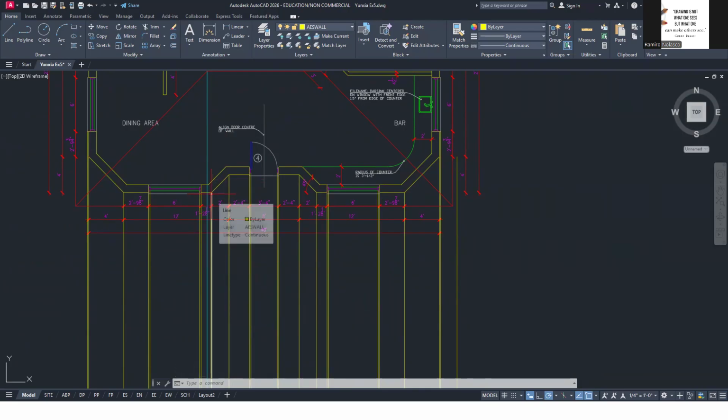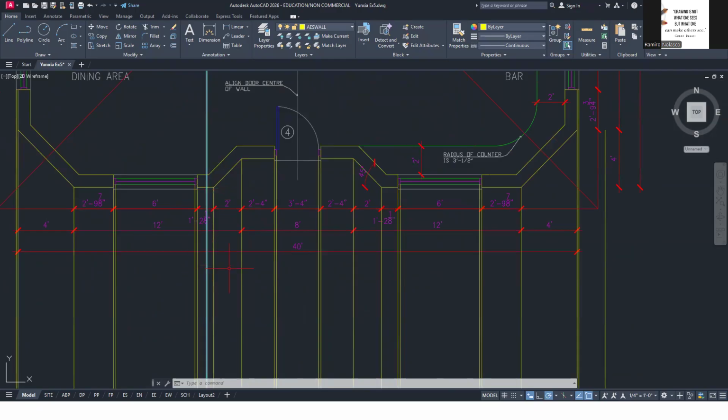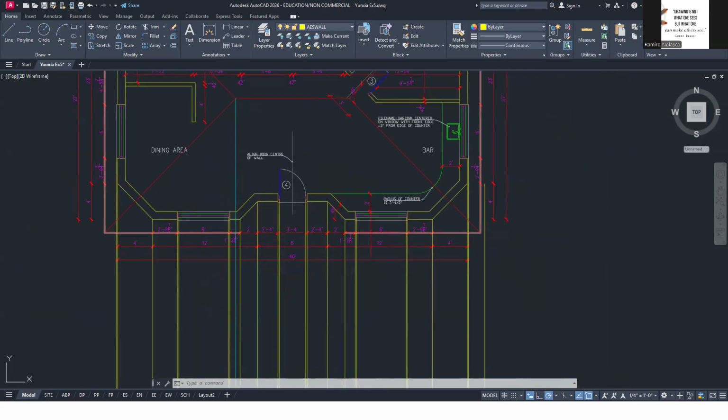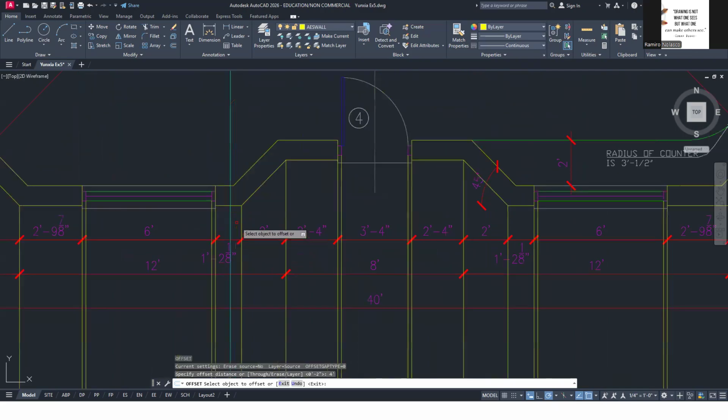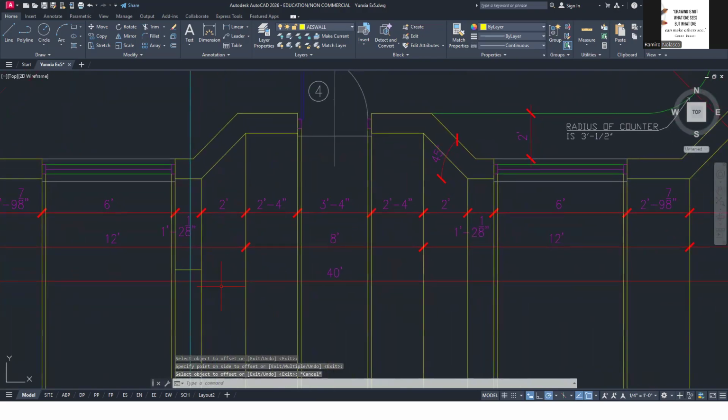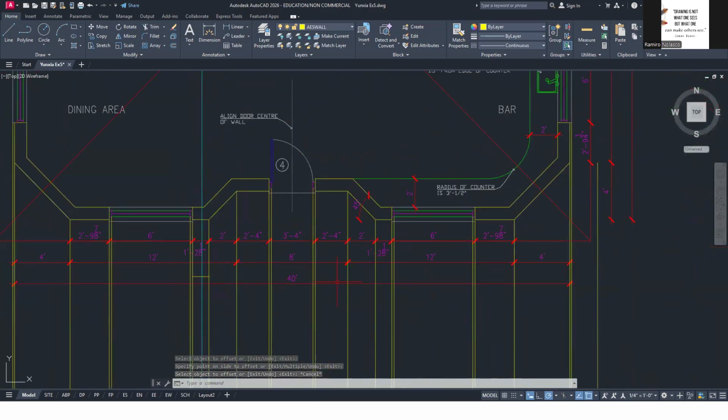Well, first we project, offset this by how much of a canopy do you need. So we already have a 2 feet offset, and then maybe another 2 feet for the canopy. Okay, so that makes it 4 feet. We have our roof right here, and we're going to project it by another 2 feet. Okay, so I'm just going to say offset by 4 feet. I'm going to offset from the wall down here. Okay, so that will be my canopy.